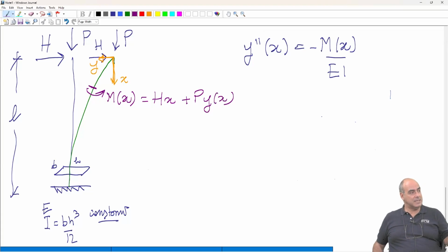The other thing is that, as we have said before, we know how to calculate the displacement due to h, but then there is p, and p has an effect on that. So we do not actually know how much that displacement will be. If we choose any other reference system, we will be forced with an undetermined question, a question to which we do not have an answer. How much is in total that deflection there, as the sum of the effect of h and p delta? Since we are not able to provide an answer to that, we just put this reference system.